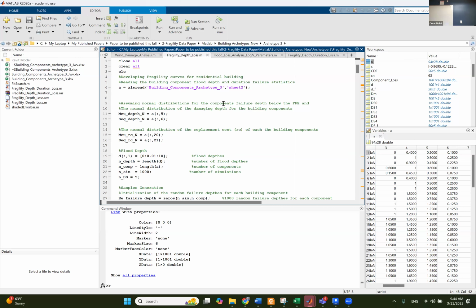Just make sure that you have a folder. This folder has the Excel sheet that you have, and also has this MATLAB code. You are going to start from the MATLAB code file, new MATLAB folder, and then make a new script. Once you hit new script, save it in the same location that has the Excel sheet, so that when I ask MATLAB to read an Excel file, it can find it. If it's not in the same folder, it's not going to read it.